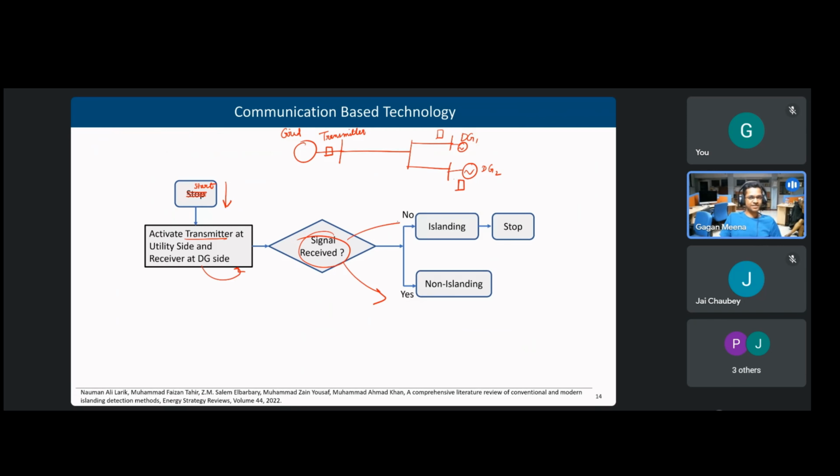After these islanding detection techniques, we discuss protection issues in smart grid. We discuss four major types of protection issues: dynamics in level of fault current, bi-directional fault current, false tripping, and blinding of detection. We'll discuss them after discussing the questions. Do you have any doubt in these four protection issues?